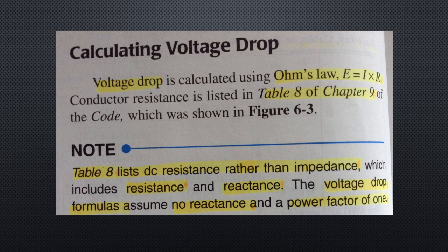Voltage drop. Most electrical equipment is sensitive to variations in line voltage. In order for the equipment to operate effectively, it is important to supply the correct voltage. The code suggests but does not mandate a maximum voltage drop of 3% for any feeder or branch circuit, and a maximum combined voltage drop from service entrance to final utilization outlet of 5%.